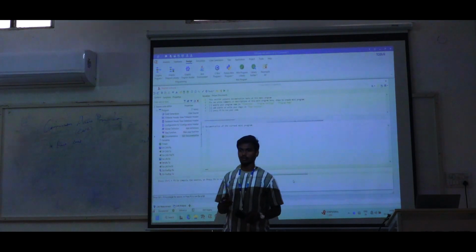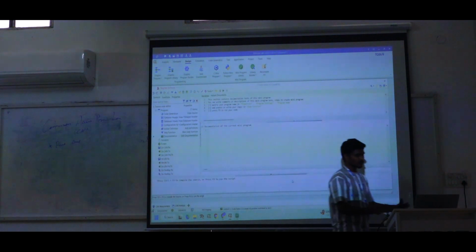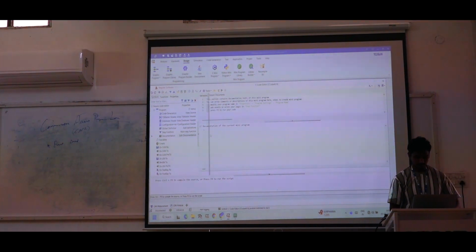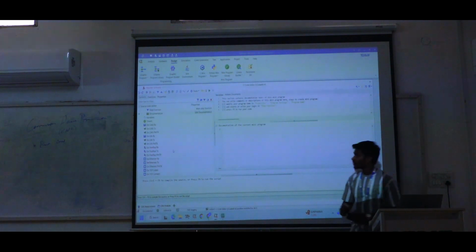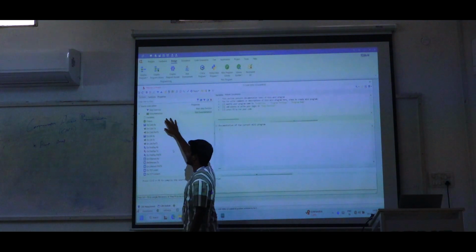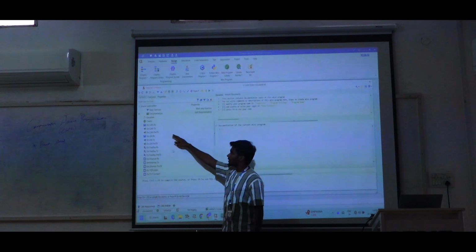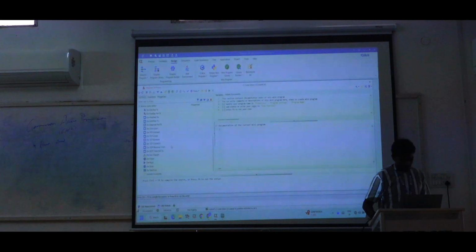Now we have triggered the event. Here the event stands for things like timers. The variable is an event, timers are an event, on CAN is an event, on CAN pre-Tx is an event, and there are also start event, stop event, on timer, and on variable change.